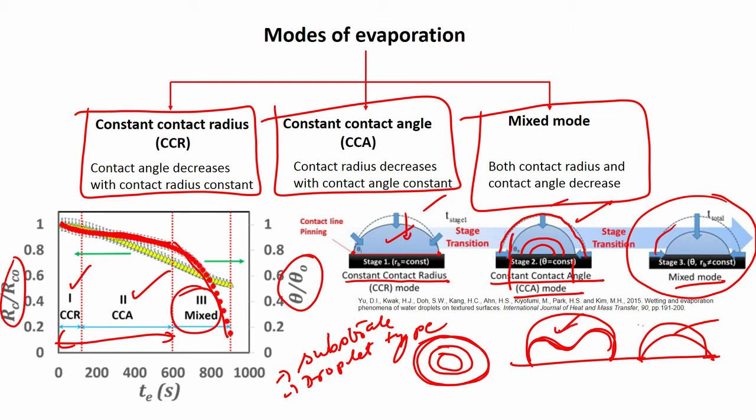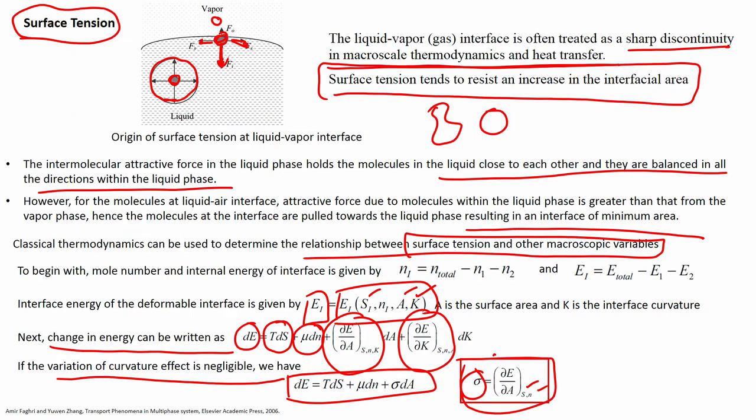Though technically conservation of mass allows both configurations, it is not permissible because surface tension tries to minimize the surface area. It is given in this particular form. There are alternative definitions as well, coming from a macroscopic equilibrium point of view. So, this is a very important concept which puts a limit on how a droplet should actually evaporate, in any field. It can be a pure conduction or a diffusion driven problem, it can also be any other type of problem as well.